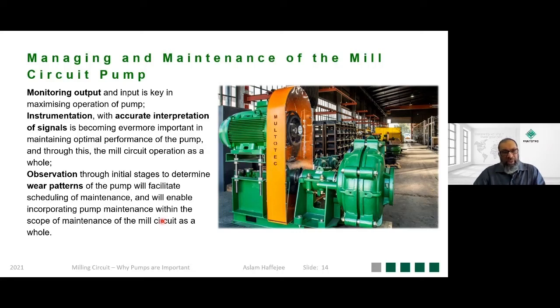But now the important thing, and this is why I'm bringing up observation, is you need to monitor what sort of pattern the pump wear develops. If it's a couple of months, as opposed to your mill, you need to fit so many overhauls of the pump within a big shutdown, maybe for a mill change out. This can only come through with monitoring and observation. Any new plant is different, every ore is different, the hardnesses are different, the wear rates would be different, and that can only come through with monitoring and observation.